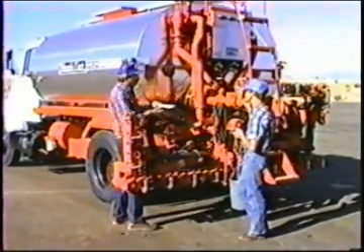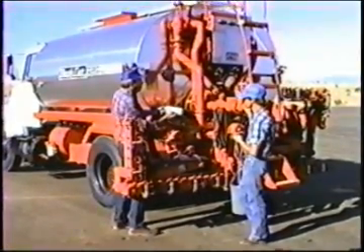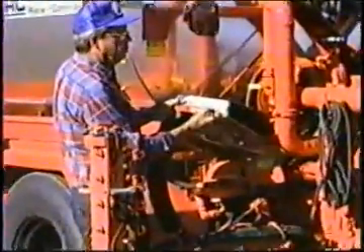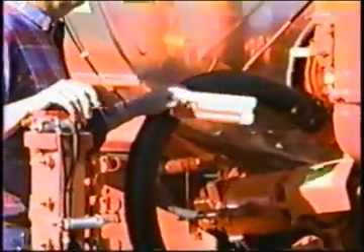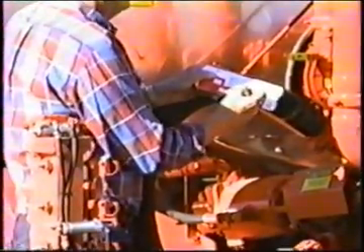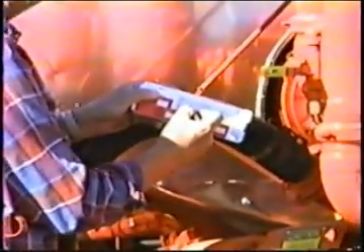Now, if we had this back section all filled in, that is the feet per minute in the particular gear at a particular engine RPM, then we don't have to make a dry run. Let's say that on this particular truck we looked down and saw that at 1200 engine RPM in the second gear, we saw 400 feet per minute.